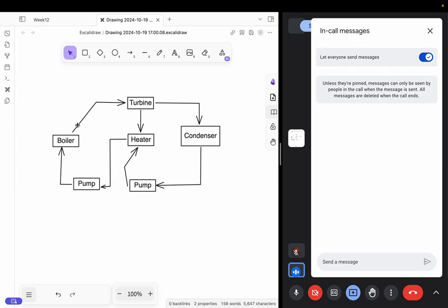But the disadvantage is that only a part of the turbine flow is sent here and the remaining part is going here. So the power output of the turbine will get reduced because the mass flow rate is reduced. So the net power output will also get reduced. This is a trade-off that you have to balance. There will be a reduction in the total power output, but also a reduction in the amount of heat supplied. So the efficiency can be higher or lower depending on that ratio, and that ratio is what you can express in terms of the increase in the mean temperature. So we'll calculate that in this problem.